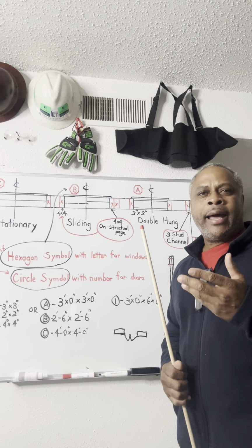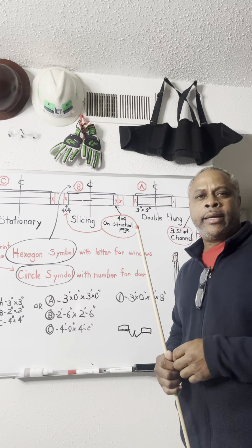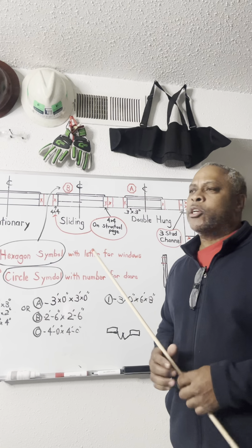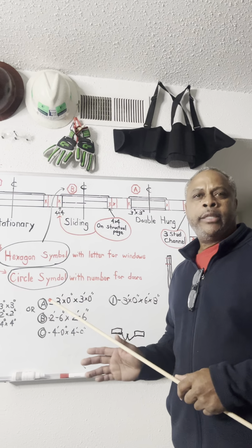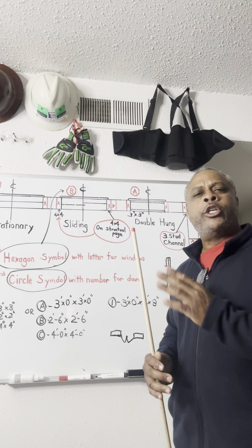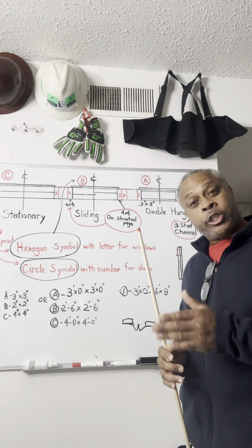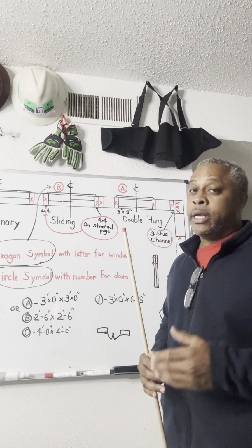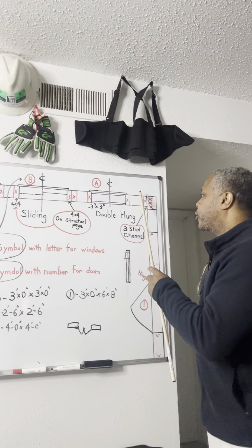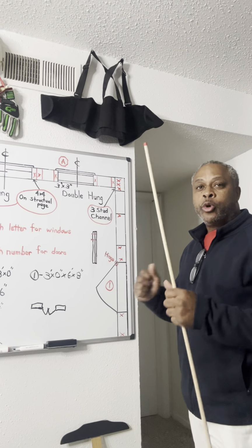You're only dealing with a 7/16 of an inch when it comes to plywood on the outside. Have there ever been 5/8? You're getting into custom building. That's a very thick plywood. Normally not. Your plywoods for your structural shear panel is usually 3/8 to 1/2 inch, which is 7/16 of an inch really, when you're putting it on the perimeter, on the outside for your structural shear.